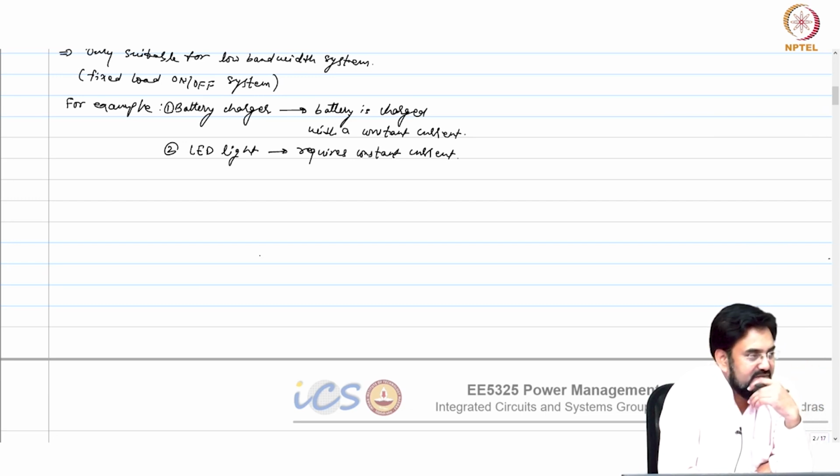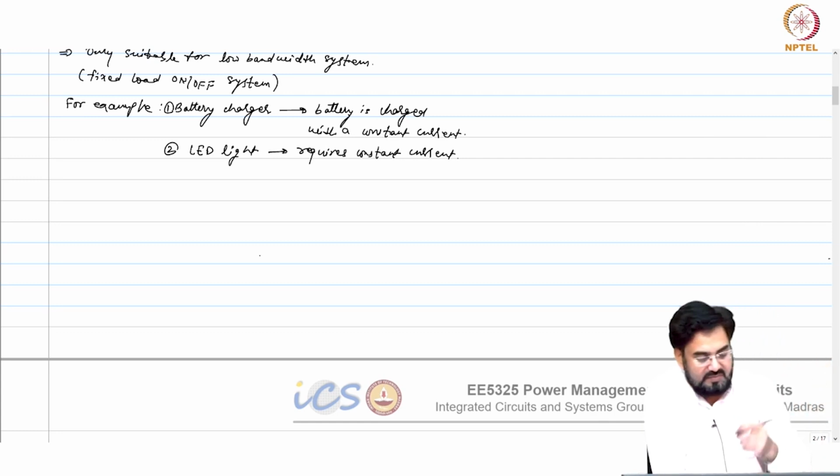But how many poles do we have here? So, an integrator by default we need, okay, because we need a very high DC gain. Other than the integrator we have 2 more poles, so we have 3 poles here. Okay. So, which means we have to introduce at least how many zeros? 2 zeros, because within UGB we can have only 1 pole. So, 2 poles we have to cancel. So, the next one is type 2.